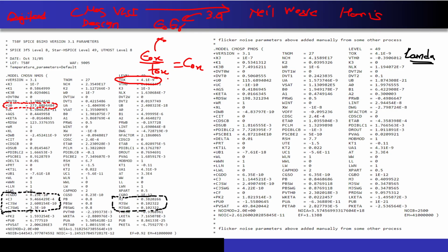Yes. And along with that, I had also told you that the CdB varies as CdB naught upon 1 plus some potential, a constant built-in potential, and some bias voltage across the CdB over here. And it was varying with the factor M. That M we have also seen. This is the same M that you are seeing in the PDK. Correct? Now, if the professor wanted to make your life hell, he would have asked you to calculate these CdB from these MJ, MJSW, CJ, CJSW.